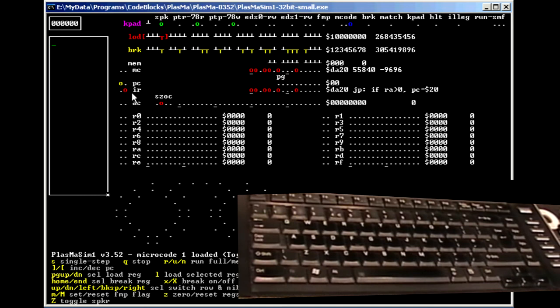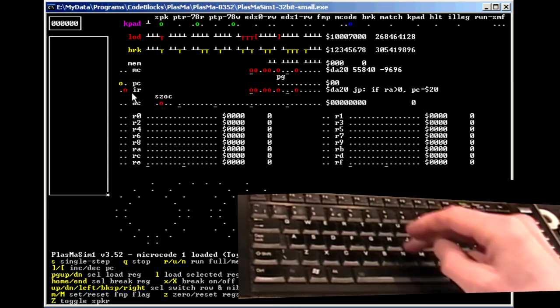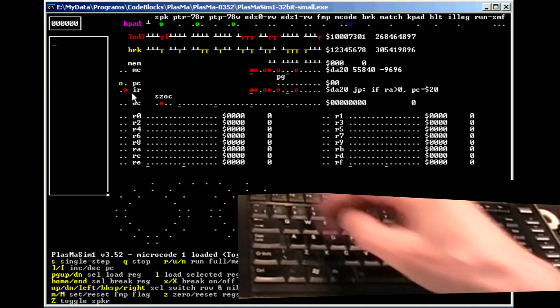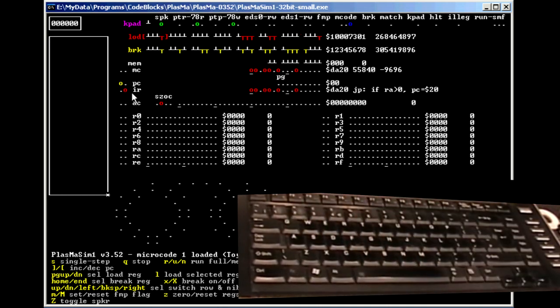Okay, we'll start with an instruction to load a value of 1 into register 3. So we make sure the highlight is at the correct position on the load switches. We need the least significant 4 nibbles, as all toy A instructions are 16 bits long. Then we just enter the instruction. 7 for the opcode, 3 for the target register, 0, 1 for the 8-bit value.